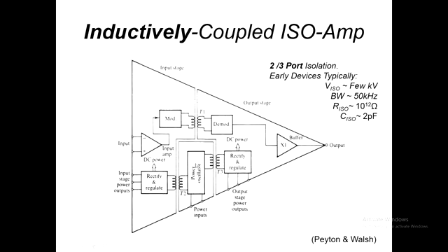So there's isolation of power supply from both input and output. The power is actually pumped across the isolation barrier via this magnetic coupling. So there's signal coupling in a magnetic form across an isolation barrier, and there's also power for the input stage and power for the output stage, done as well, magnetically coupled across an isolation barrier.